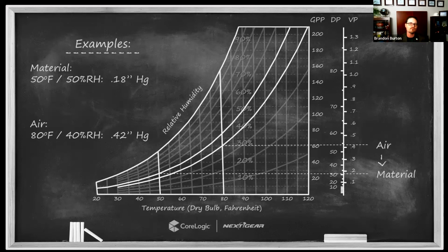the relative humidity measured by that hygrometer that was contained to the surface of that material, that relative humidity is dictated by the amount of moisture in that material, how wet it is. And it wouldn't matter what the surrounding temperatures were. That humidity will remain the same as long as the amount of moisture in that material remains the same. In other words, I could make the material warmer. It's still going to give me a 50% relative humidity. I can make the material colder. It's still going to give me a 50% relative humidity.